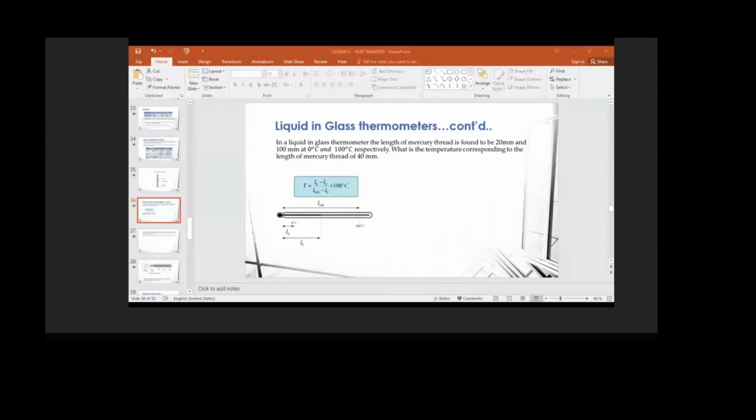So what this means is that if you're using it for a long period of time, then because of the heat that it produces, it will cause a problem with the accuracy of the measurement. Right? So these resistance thermometers are only to be used for a short period of time. When you're finished, you turn them off, so the heat does not affect the correct temperature that it should give.